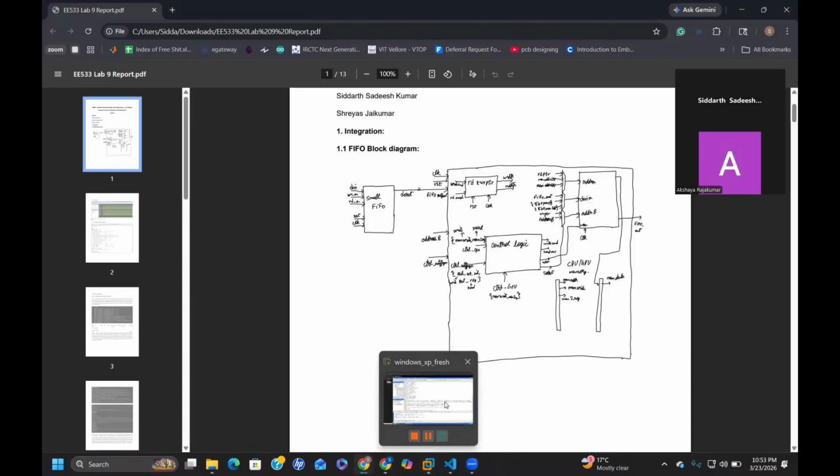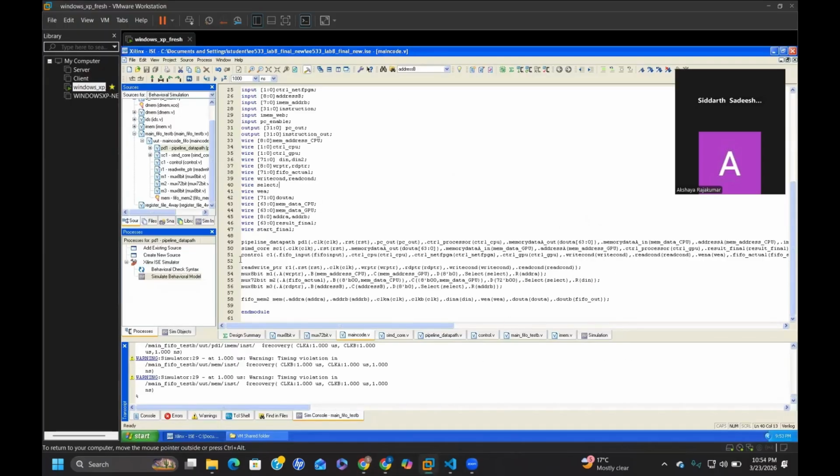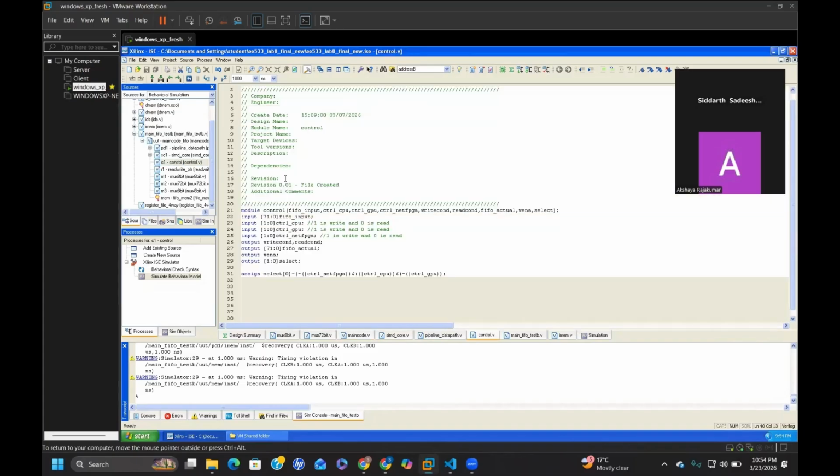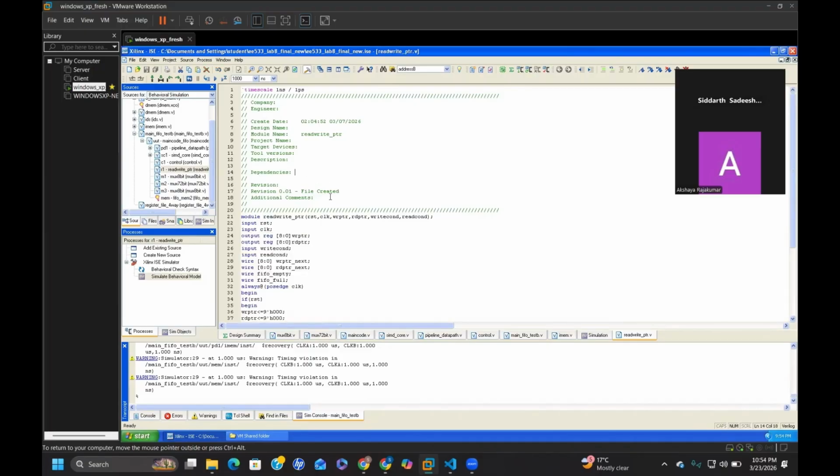So here, this is the control logic. I'll show you the control logic now. It's pretty simple logic for the select lines. Basically, you build it with a basic combinational circuit. Similarly, for write enable, if any of them want to write, the write enable goes to the FIFO. Similarly, for the write condition and read condition of NetFPGA, this is important for the read and write pointers, which I'll go into next.